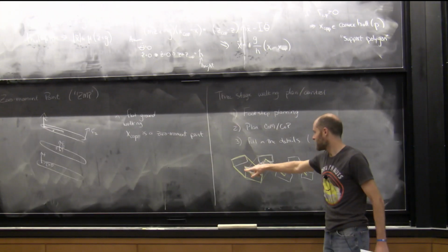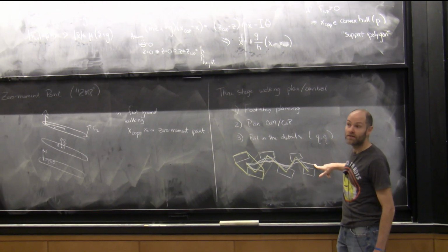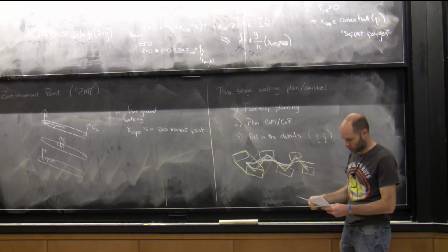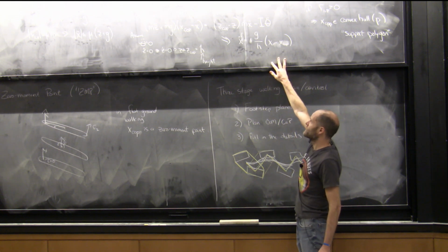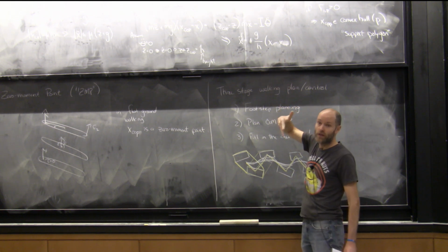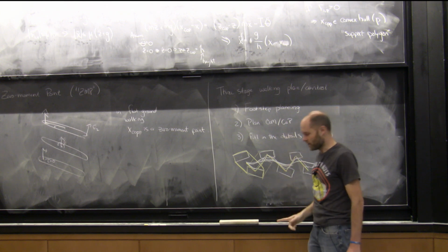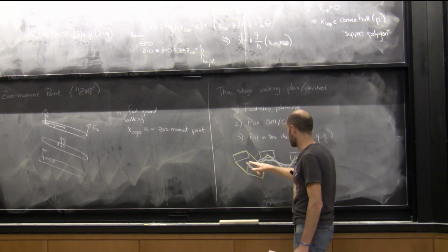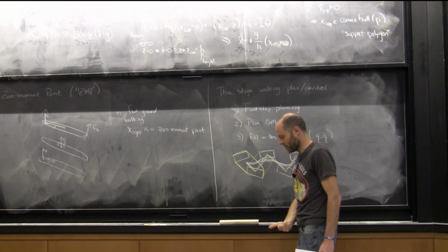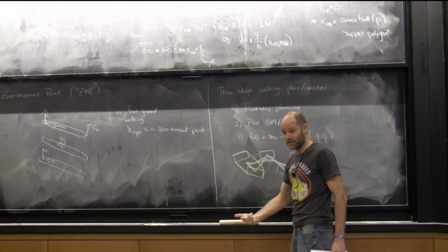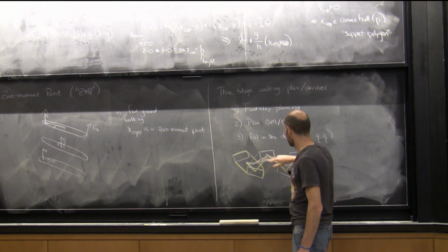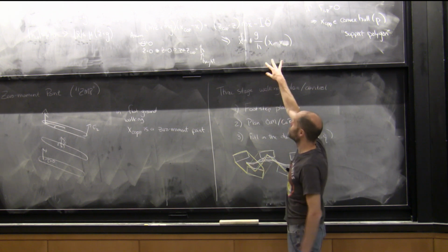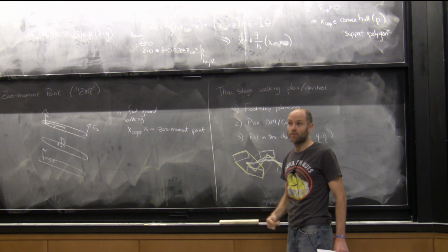It demands less of your control system to walk fast, and it's partly because your center of mass trajectory is less, and it's implied right from those equations. By the way, I wrote down just the planar version of this, but this works in 3D also. And the nice thing is that the dynamics of the center of mass in the y coordinate are completely independent, given this model of the trajectory in the x coordinate. So these equations are just two of those equations: the x double dot and the y double dot.